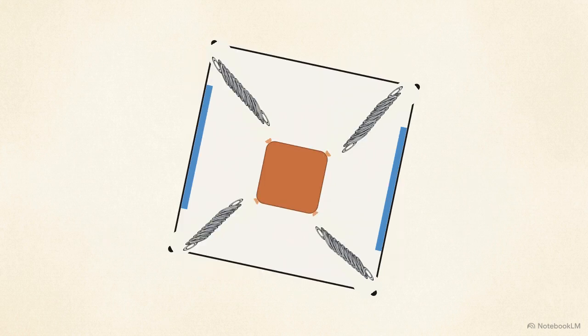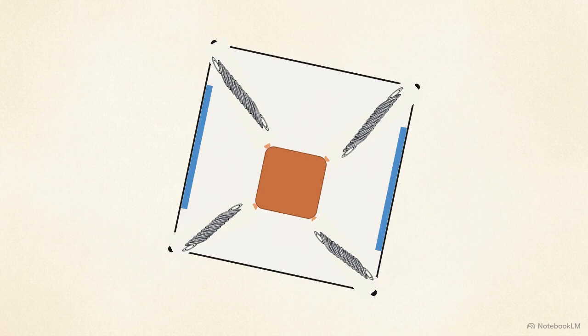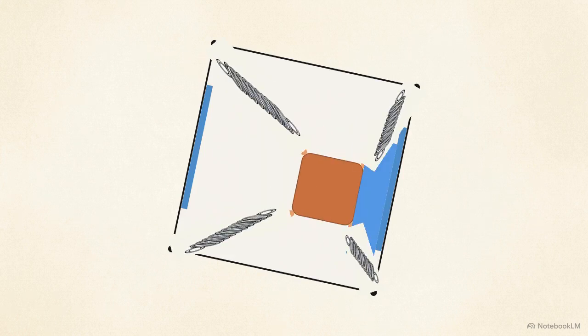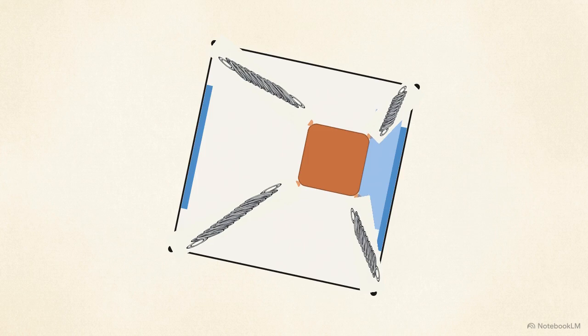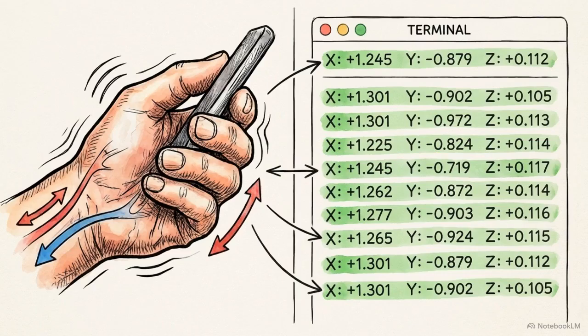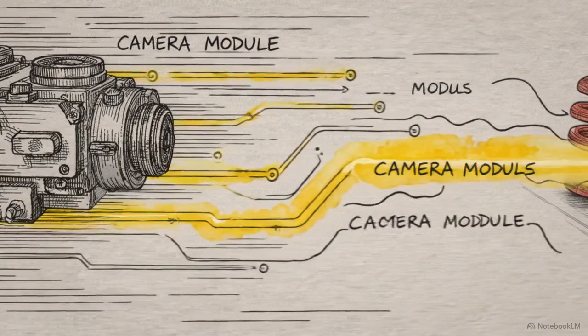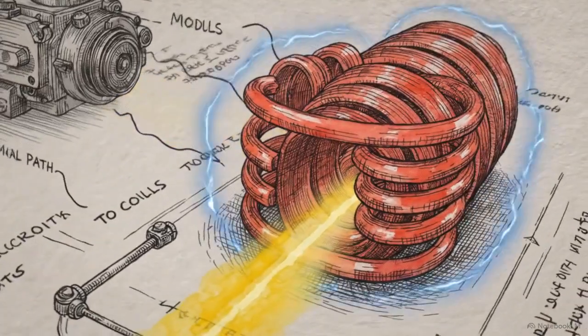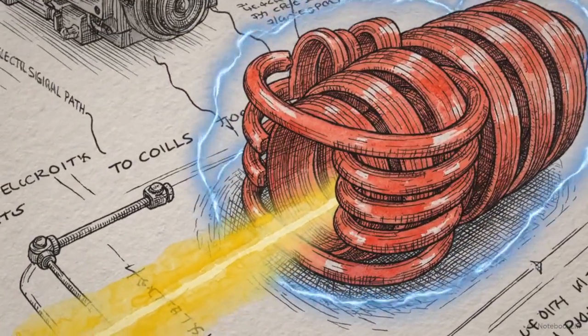When your phone tilts, the system rotates. The Coriolis effect pushes the mass laterally against its springs. This shift changes the electrical capacitance between contact plates, instantly generating exact pitch and yaw coordinates. Through this mechanism, the unpredictable shaking of your hands is instantly quantified into exact mathematical data. Those exact coordinates are immediately fired from the gyroscope brain over to the system's muscle, tiny electromagnetic actuators.